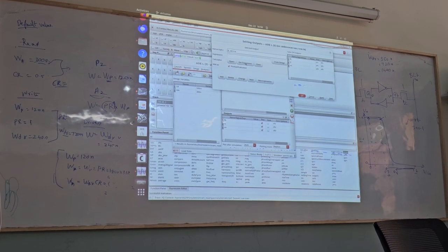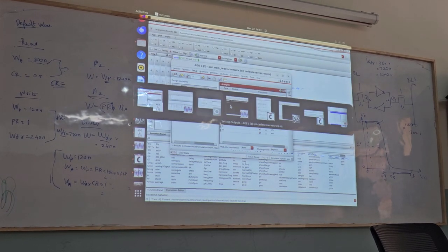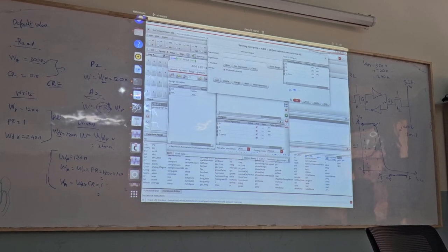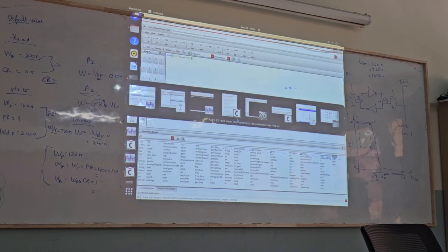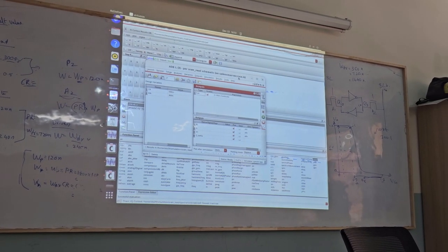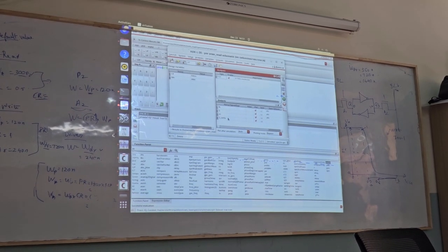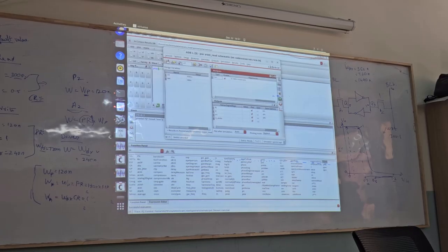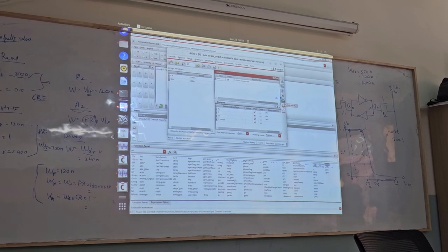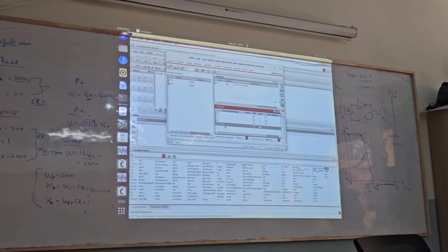Yeah, so now when I click on this get expression, whatever is there in the buffer, in this calculator, will get copied. Okay, so I just click on this get expression, and that expression has been copied. Click on add, click OK. So once this is done, we can just get back here to our ADE window. Now whenever we define an output through output setup, how do we get a graph out of it? Can I use this play button that is available in the ADE, or do I need to perform some other analysis? How do I get a graph for this newly defined output expression?